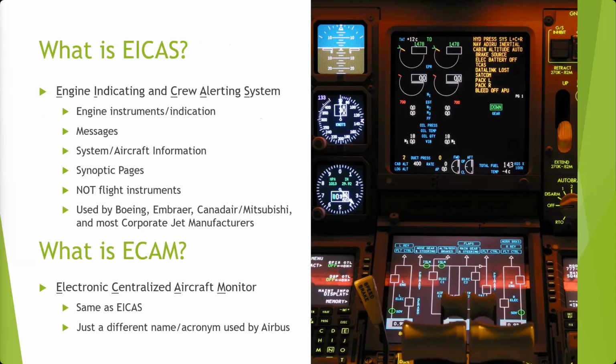Don't remember what aircraft. I want to say it's the 170 or the Legacy again. Something with Pratt & Whitney engines, or it's got Rolls-Royce engines on it. Doesn't have GEs because it's got an EPR gauge at the top. GE uses N1 for its primary power setting, and they don't show EPR typically.